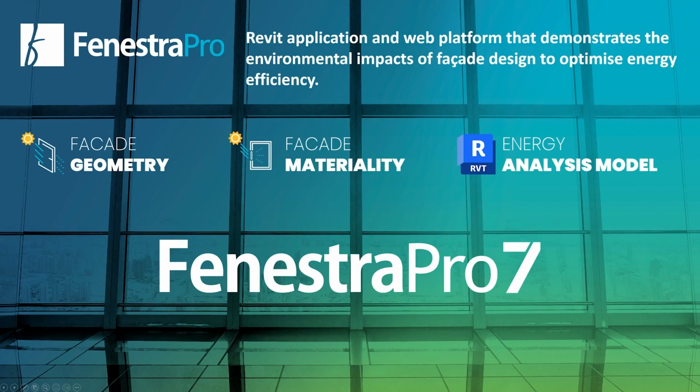So FenestraPro is a Revit application, as you know. It's a web platform that supports that application, and it demonstrates the impacts that your design decisions have on the energy efficiency of your building. So it'll do that by leveraging Revit, and we've heard a lot about Revit and the analytical model and stuff like that, but it leverages that by looking at the geometry and the materiality, and not just looking at them, but driving them as well. So it's a two-way thing. It's reading from the model and pushing back to the model, and very much looking at that energy analysis or analytical model that Ian was talking about.